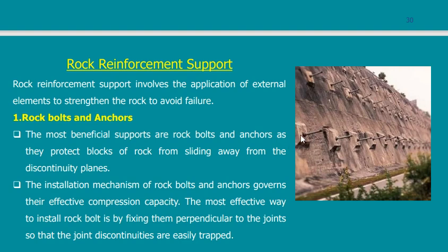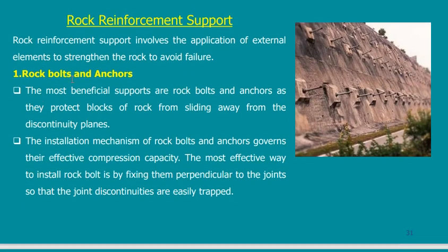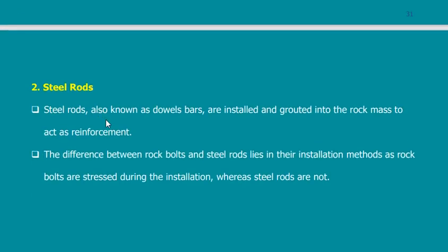I go to this soil here, I drill a tube and remove the soil from inside, I put this nail or this bolt inside and I cover it with mortar. Once this mortar dries, this bolt will be as if I'm adding reinforcement to this block. So this is the first type, adding rock bolts or rock anchors.